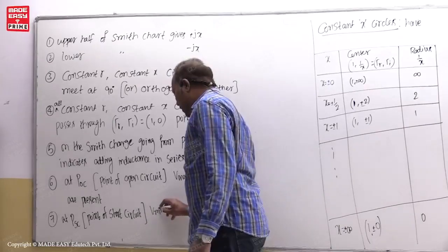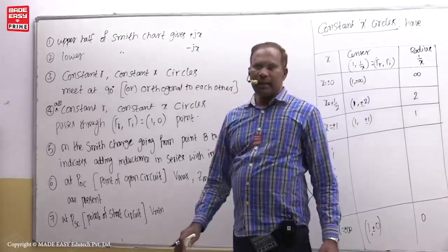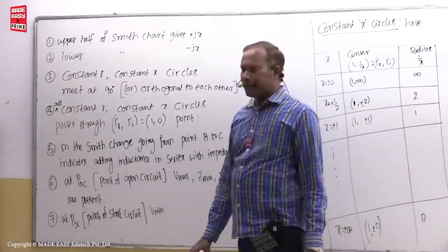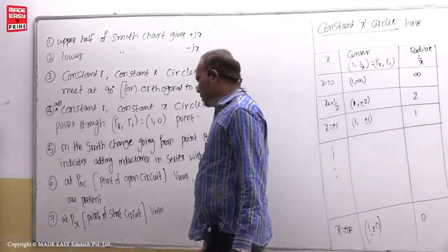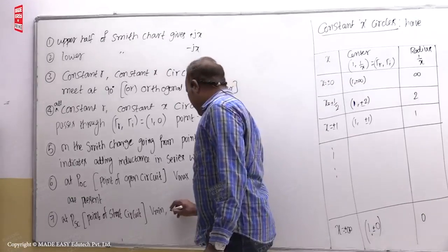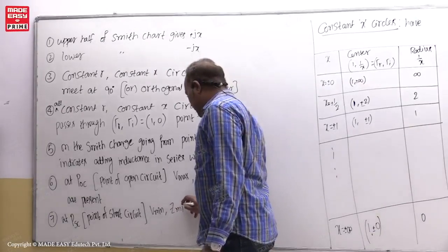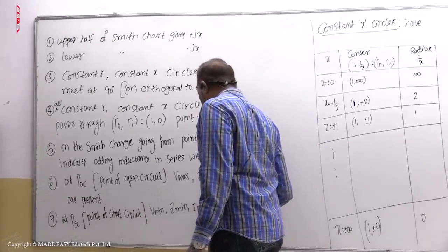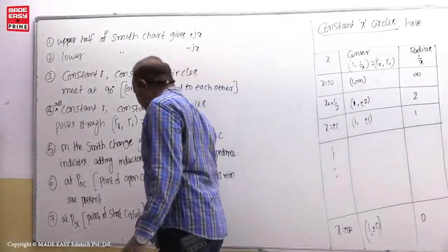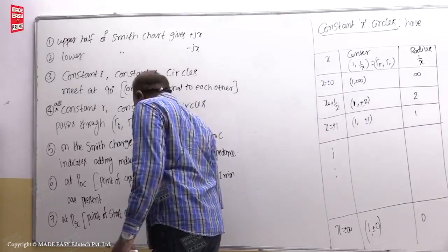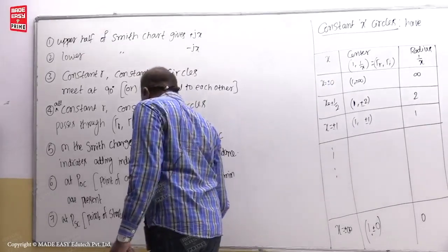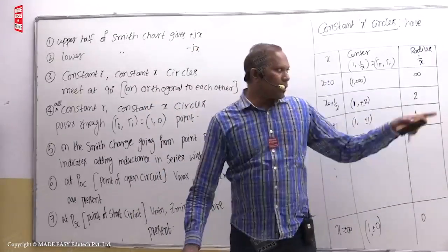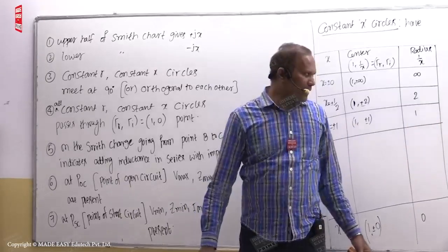voltage is minimum. We have studied these things in theory, no student. Representing theory in diagram form is nothing but Smith chart only. From equations only you got that one, na? So V minimum and Z minimum, I maximum are present. So already you know that at these two locations SWR is infinity. Already I wrote there SWR infinity at those locations. Okay.